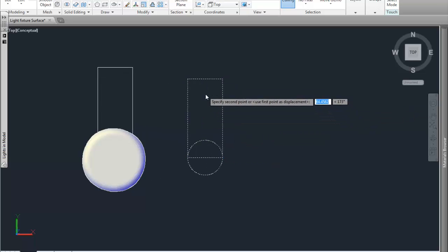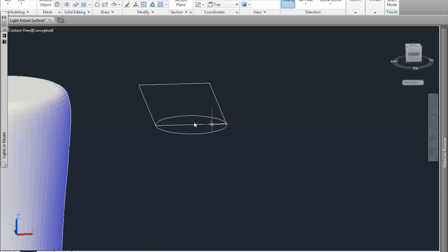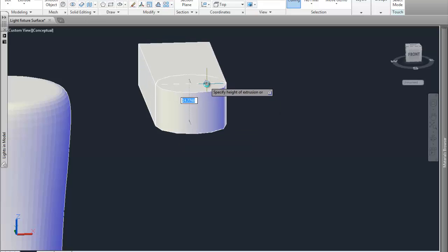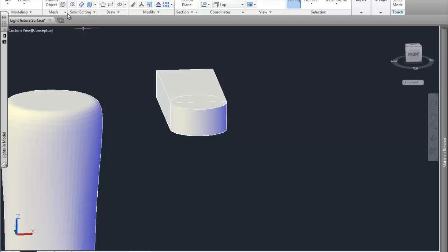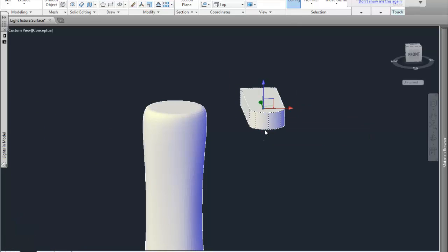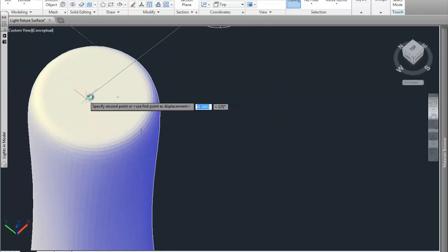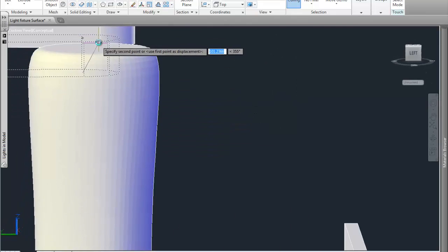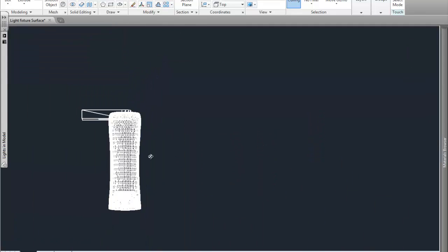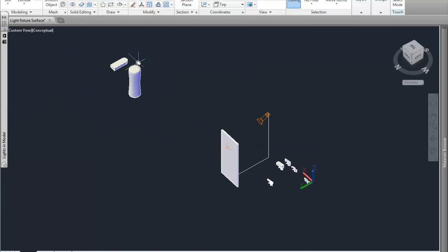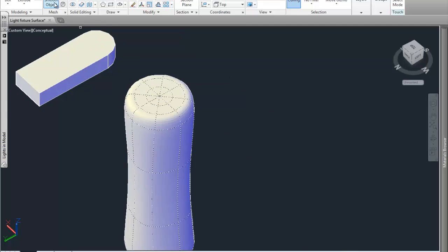So if I had it over the object, you can't see it, but I'll extrude it out now. There we go. And I can just union it together, giving it one single piece. From there, take the center point and I move it over to here, which I can't grab the center point because there is no center point. So I'm going to have to work out some idea of making a center point, such as, I might uncrease this. So I'd use the uncrease or smooth less.